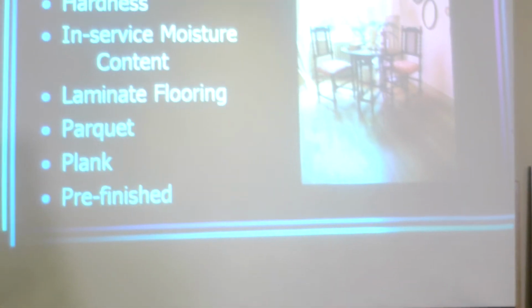Floating, that's a good way to lay a floor. Floating is where the floor is not fixed to the subfloor. In fact, it's only fixed to each other with glue. So your floor essentially floats. It becomes one big panel floating in the room. And it's something you would only do with engineered, never with solid.